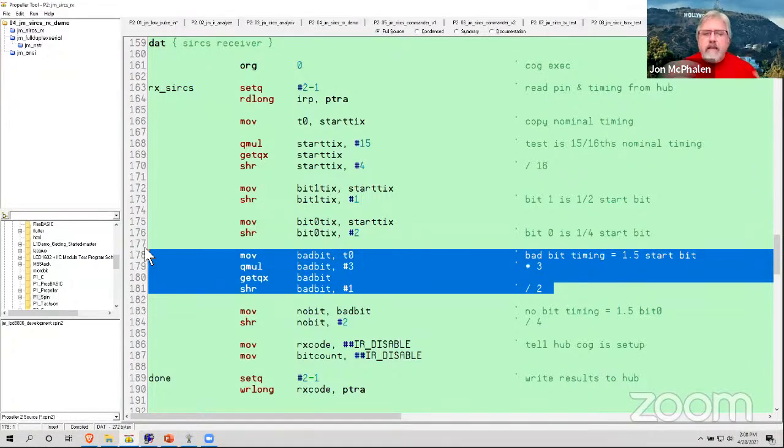The reason behind that, after I got in with an oscilloscope to find out, is that the PIC, nice little processor, but the way that it does frequency generation is not as precise as what the propeller can do. So even though in the case with the taggers we're using 56 kilohertz, the frequency that was being generated by the PIC was a little bit off of that. And you'll remember from that diagram, that slope is fairly steep. So the farther you get away from the center frequency, the less sensitive your receiver is. And in fact, we use that in the tagger.